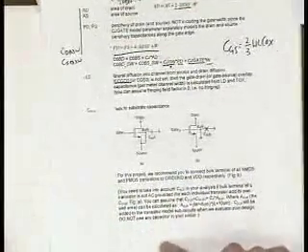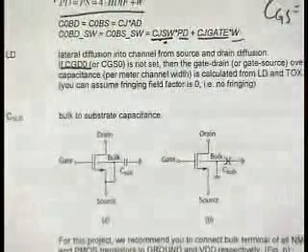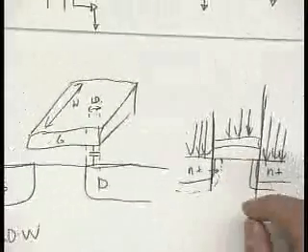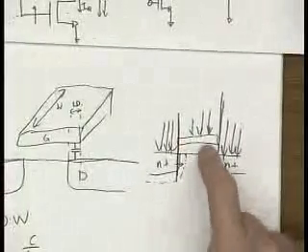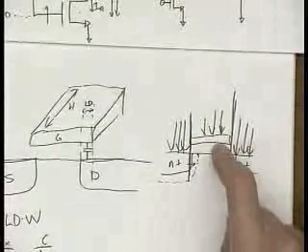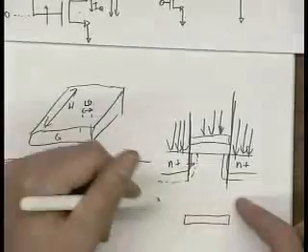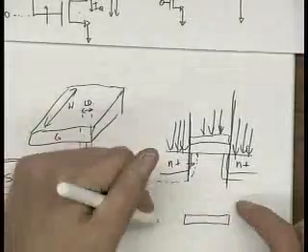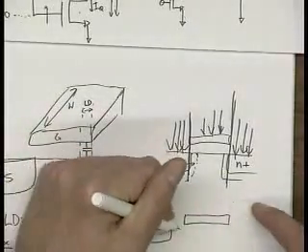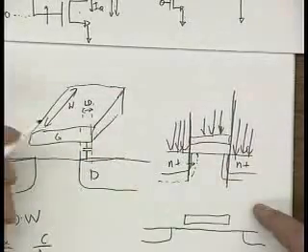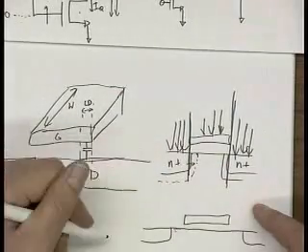Good question, though. All right, and so finally, why don't they make up for the lateral diffusion by bombarding a little bit away? Because they can't, because they're not using a separate mask. They're actually using the gate as a shield. So you're suggesting pushing it further away. What would happen is, let's say you did this, and then you anneal to get it to align exactly.